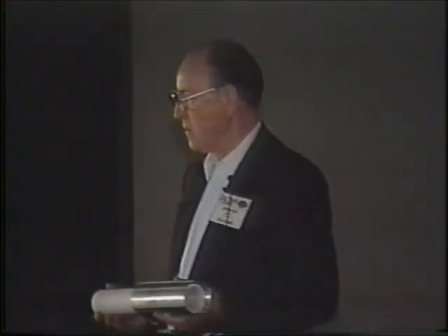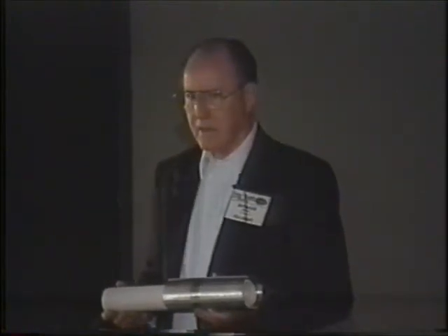Now, this is one way to tune these things without having to figure all of the other characteristics that have to go into it, which gets pretty complicated sometimes, and especially because resistors, although you think resistors are resistors, if you take your LCR meter and you measure the capacitance and the inductance of almost any resistor you're going to run into, you'll find out that the resistor is a lot better capacitor and a lot better inductor than it is a resistor. And those things vary considerably from one resistor to another, and the only way you can get around that is get non-inductive, non-capacitance resistors.